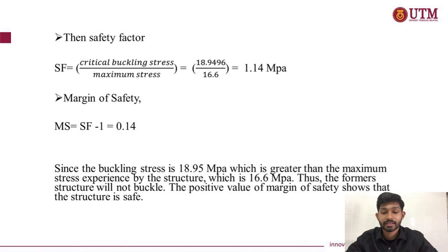Since the buckling stress is 18.95 megapascal, which is greater than the maximum stress experienced by the structure, thus the buckled structure will not buckle. The positive value of margin of safety also shows that it is safe.